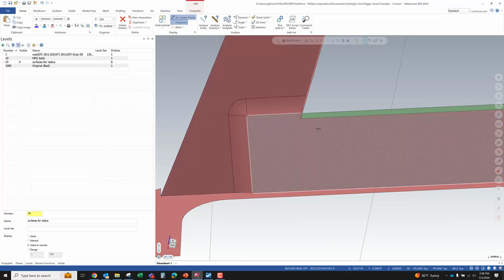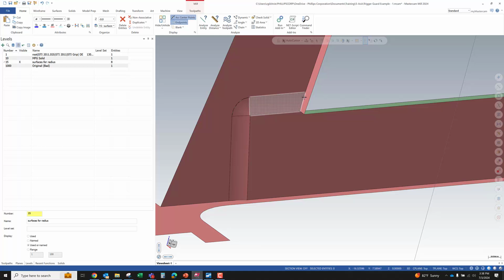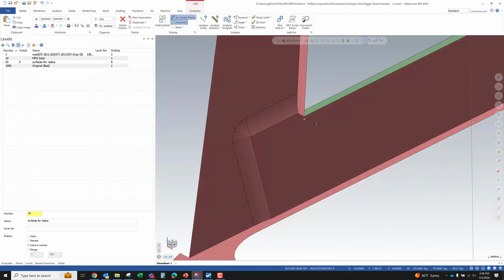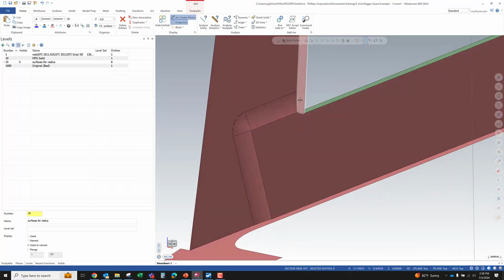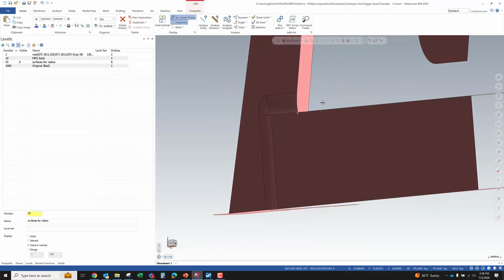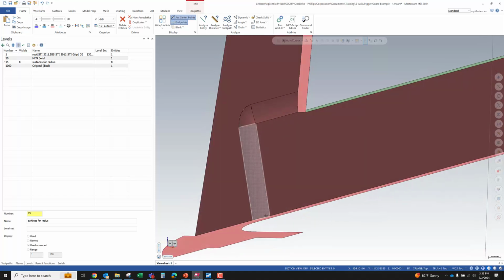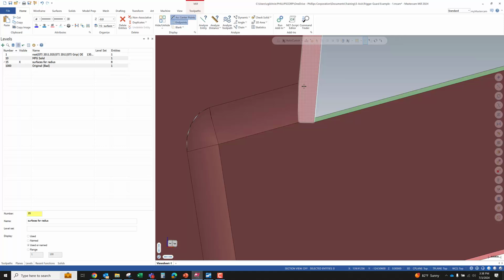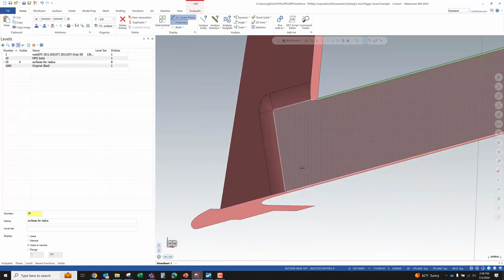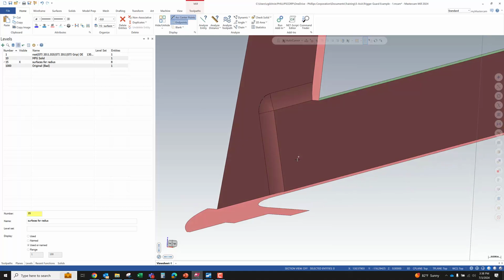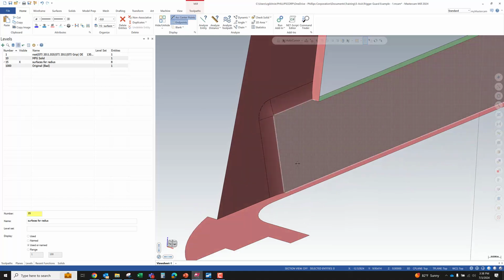probably use, the bigger end mill we use, right, the farther we're going to have to stay away from where these sharp edges are. And you have to decide, are we going to put a little fillet in here and just use a little tiny ball end mill to do it? If we were, what would that look like? What would a reasonable size for this be? 30 thou, 40 thou, 1 millimeter.